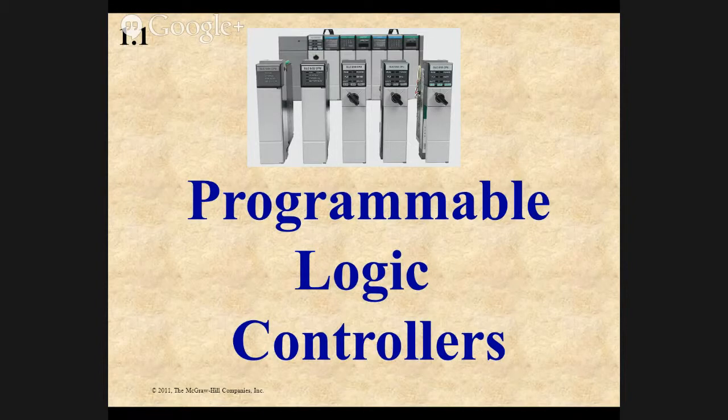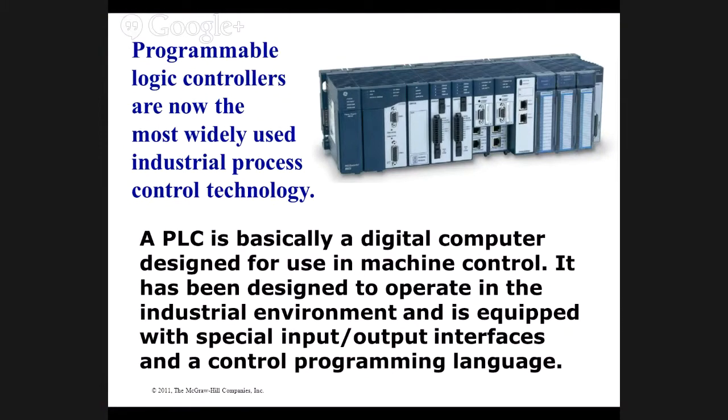So, okay. So, programmable controllers pretty much are everywhere in industry, and basically a PLC is a small computer that runs a program that you make, and basically it makes decisions on the input, the I/O, and the result of those decisions is an output. Okay, so basically inputs happen, we examine the inputs, and then from there we make a decision and turn on an output. Pretty simple, right? Yep.